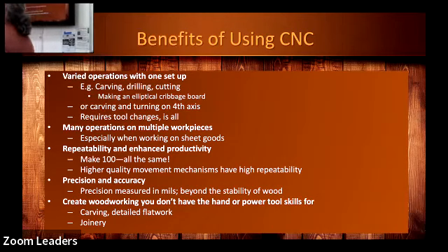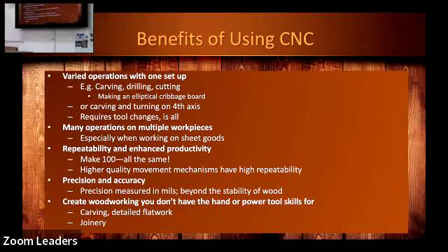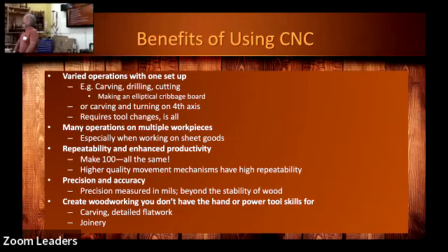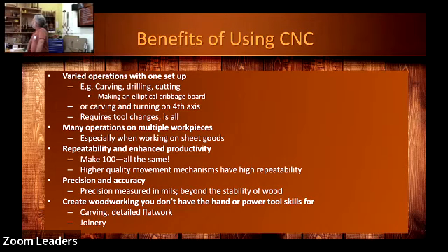If you really need square corners, you're going to have to take out a chisel. There's just no way around it. Depends on what you're trying to do. If you're just trying to make a square corner straight down, you're right, you might have to. But if you're trying to take 2 pieces of material and inlay them together, you do it entirely on the CNC, and the result will be a very sharp outside corner.